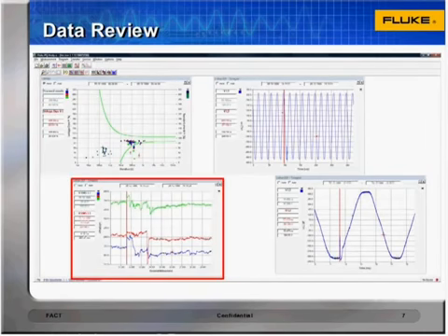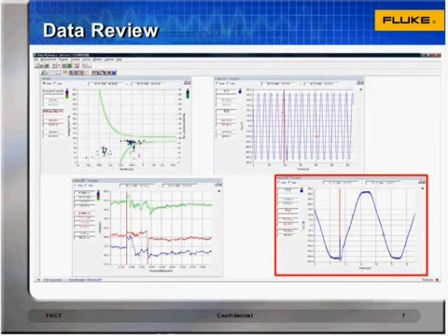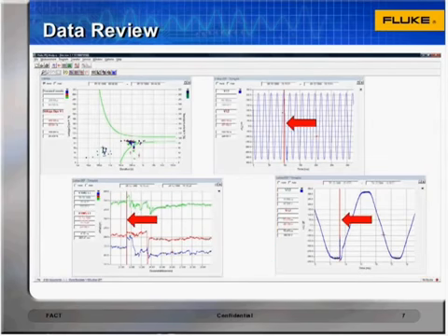The software then displayed the RMS trend plot, waveform graph, and a high-speed view of the transient. Each graph has a red marker denoting the trigger time to help in comparison. Each individual graph has tools for zooming, scaling, and measurement.